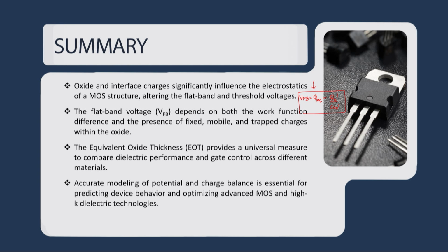So this is just an initial case to study the MOS capacitor. When you apply more voltage, whether positive or negative, to understand the implication of VGB on the MOS cap, you will take a reference, and that reference is the flat band voltage.